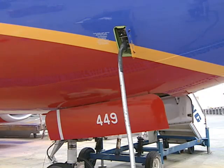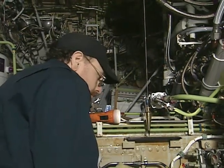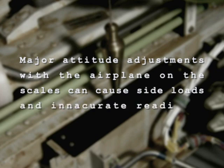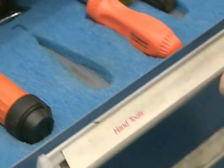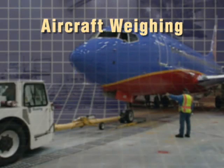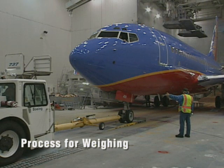In all cases, the airplane exterior should be clean and dry. Obviously, any water on the airplane will make the airplane heavier and may affect the airplane's CG. Set the leading and trailing edge flaps and slats to be either fully retracted or fully extended. Boeing recommends weighing with flaps and slats fully retracted to eliminate the possibility of damage during the weighing process. Set the horizontal stabilizer to its neutral position. Close all passenger and cargo doors and move all seat backs to their upright positions. Remove any exterior lines attached to the airplane.